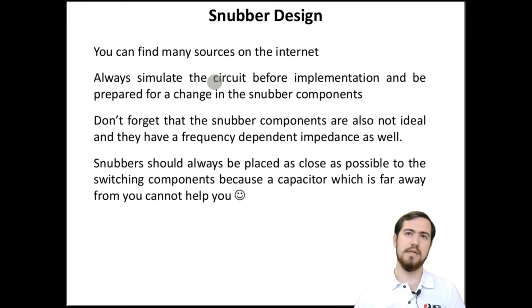There are some analytical solutions in the application notes on the internet. However, I recommend you still to check with a simulation before implementation and get prepared to have a change on the snubber components, and please make a PCB design by considering this fact, the being prepared situation.